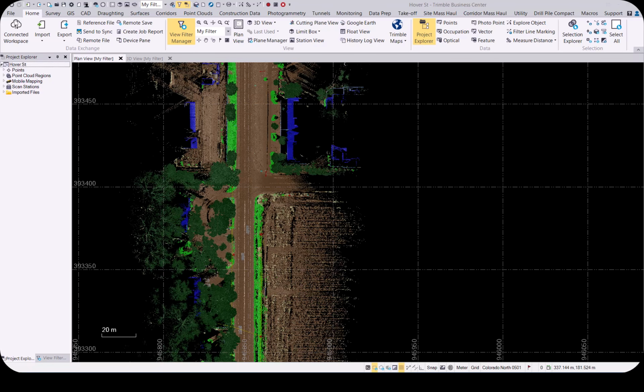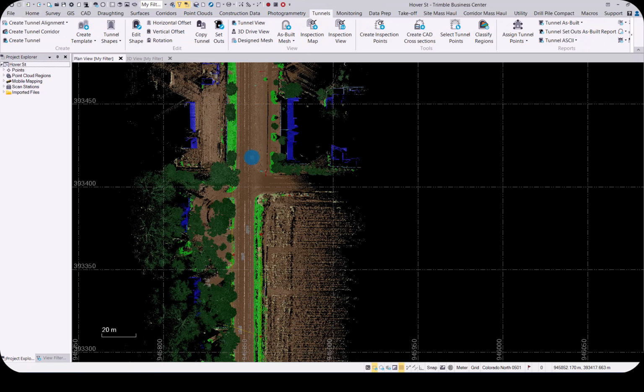Just a quick note on tunneling. We have done some enhancements there. The enhancements are on the reporting side. You will see there's enhanced analytics, reverse tunnel reporting direction for flexibility has been added, and reporting for undulations and waviness has been added for better insights into construction tolerances. We've also enhanced the inspection color map based on industry standards and ease of reporting.